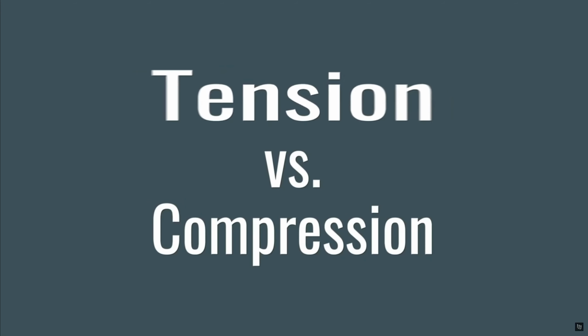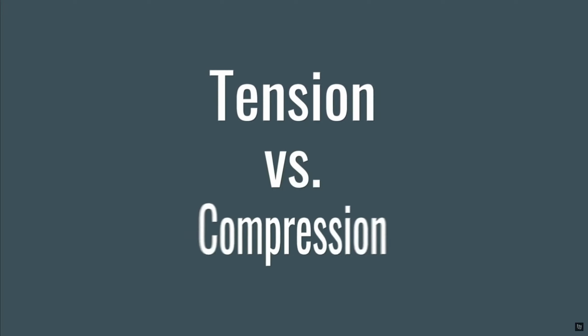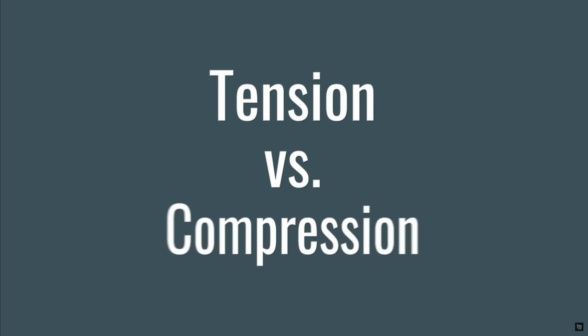There are primarily two main forces that each component, each member of a bridge is going to experience. It is either a tension force or a compression force. A tension force is basically a force that will attempt to stretch the member or stretch the component of the bridge. And a compression force is a force that will attempt to shrink the member or the component of the bridge. And so those are the two main forces that any member of the bridge will have to experience. Some members will have to experience both at the same time.